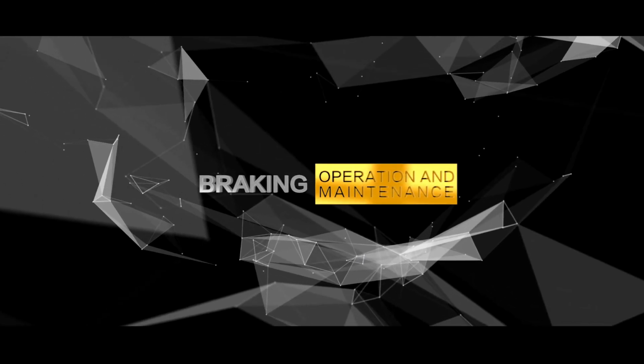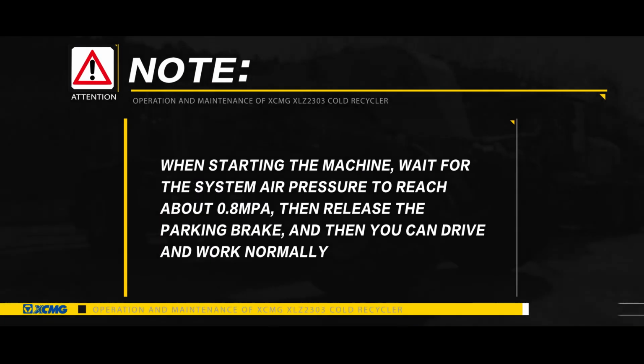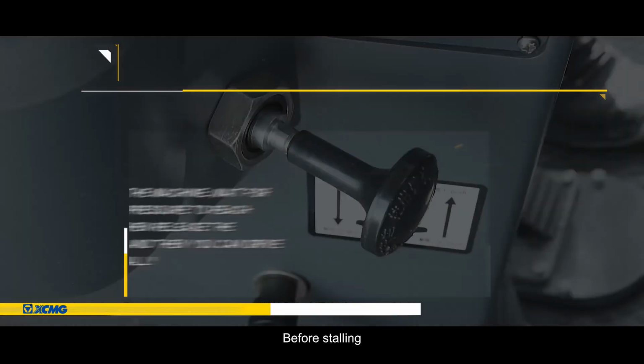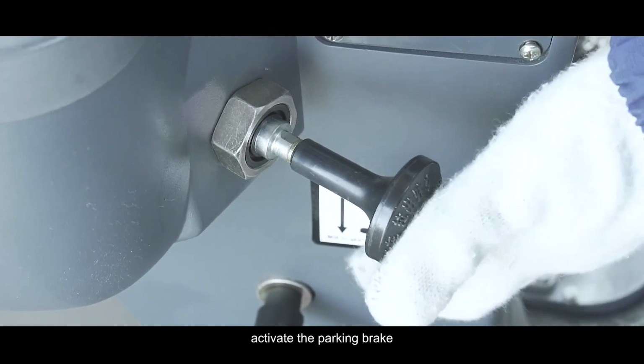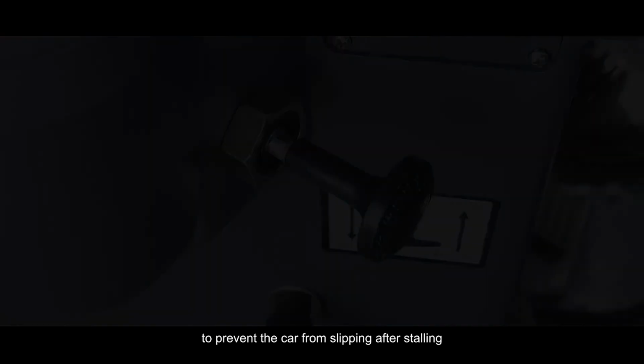Braking. Note: when starting the machine, wait for the system air pressure to reach about 0.8 MPa, then release the parking brake, and then you can drive and work normally. Before stalling, activate the parking brake to prevent the machine from slipping after stalling.